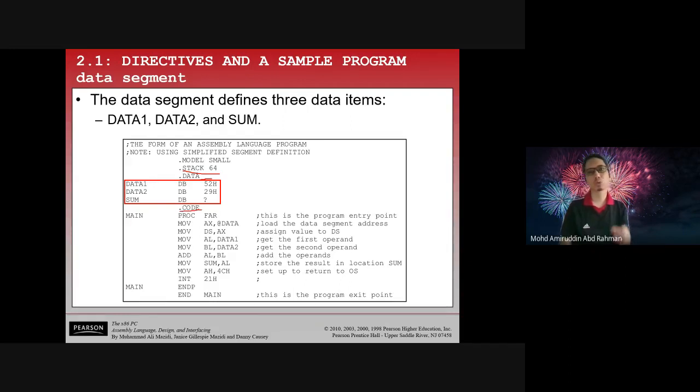Each of these segment registers is already divided for each special function. So we already learned when to use the stack, when to use the data, and when to use the code segment. In the code segment, we just put the instructions. The data segment is where we keep the data set.